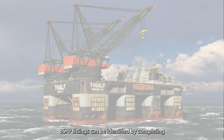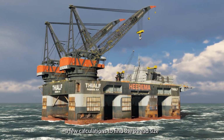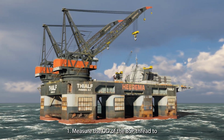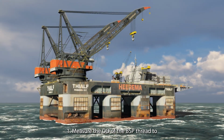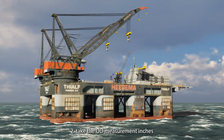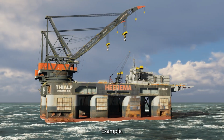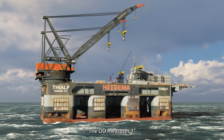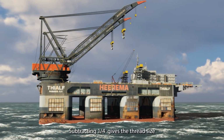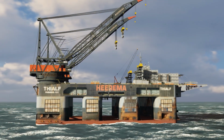BSP fittings can be identified by completing a few calculations to find the thread size. 1. Measure the OD of the BSP thread. 2. Take the OD measurement, in inches, and subtract 1/4 inch. Example, the OD measures 1 inch. Subtracting 1/4 gives the thread size of 3/4, also known as -12.